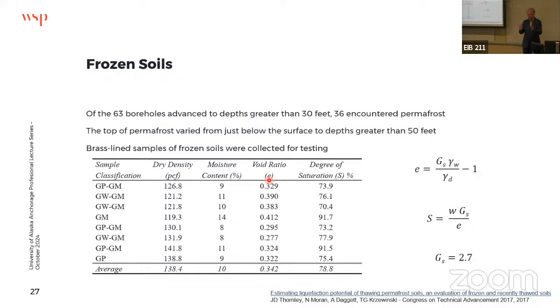But what happened in the 2018 earthquake is that the zone of fine sand that was left in place liquefied, and that MSE wall translated and actually moved a little bit. What is an MSE wall? Mechanically stabilized earth wall. Those panel walls that you see at some of the bridge abutments. They've got the little plus signs or little octagons and hexagons, so they've got reinforcement in the back. The whole thing moved, but it moved across this layer of soil that was left in place.